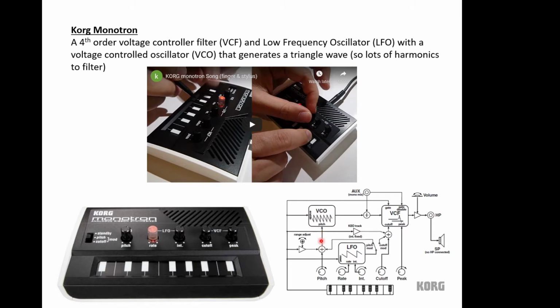So again, a DC input changes an AC parameter, and for a synthesizer this is for generating notes. We then have a voltage controlled filter, which we've just looked at, which will then filter those notes, and if they've got harmonics in them, and usually a sawtooth is used in an analog synthesizer, you can filter that out and make some very interesting noises.